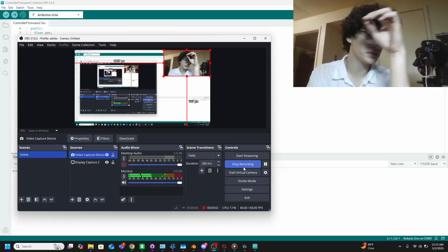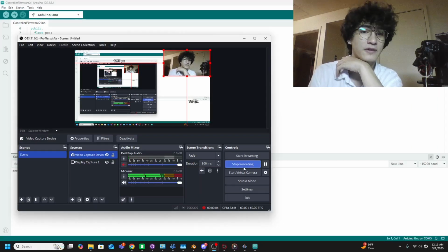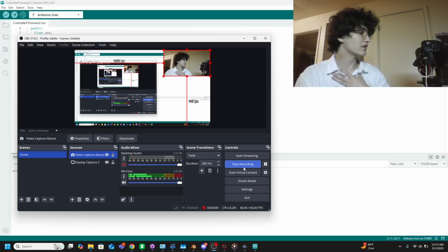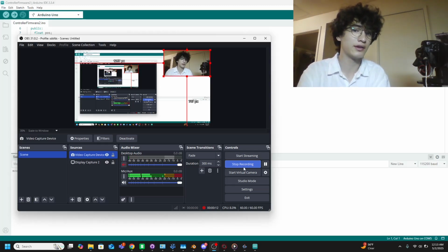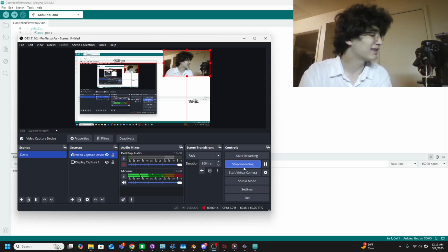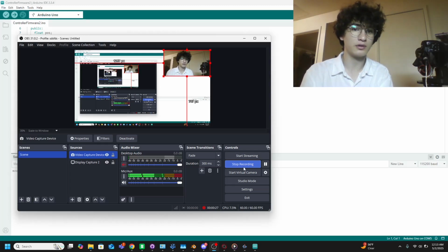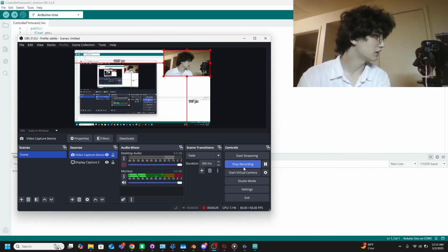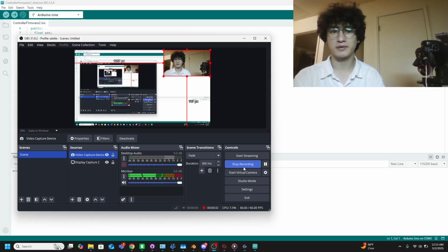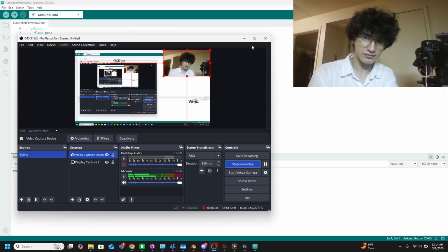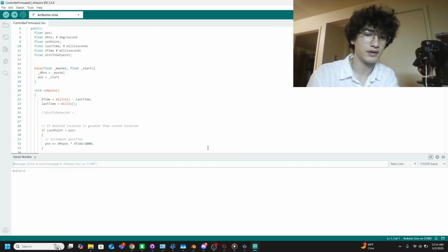Hey Joe, just one more thing I wanted to add on. I forgot to talk about how the computer actually speaks to the robot. So since I'm using a standard CNC control board and CNC control firmware, it's pretty commonplace for those devices to have the ability to have G-code streamed to them, and that is usually done through RS-232 serial, which on a software level is being emulated by the drivers.